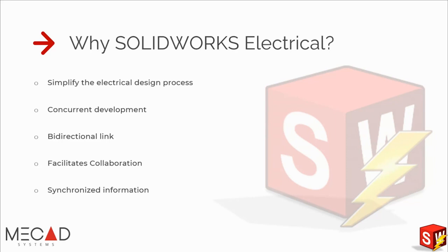And some of the capabilities of SOLIDWORKS Electrical. SOLIDWORKS Electrical schematics are bidirectionally linked to allow multi-user interaction in real time. They're also linked to your 3D SOLIDWORKS assembly, facilitating verification of a proper fit, planning of all wire, cable and harness routes, and calculation of wire lengths prior to assembly.